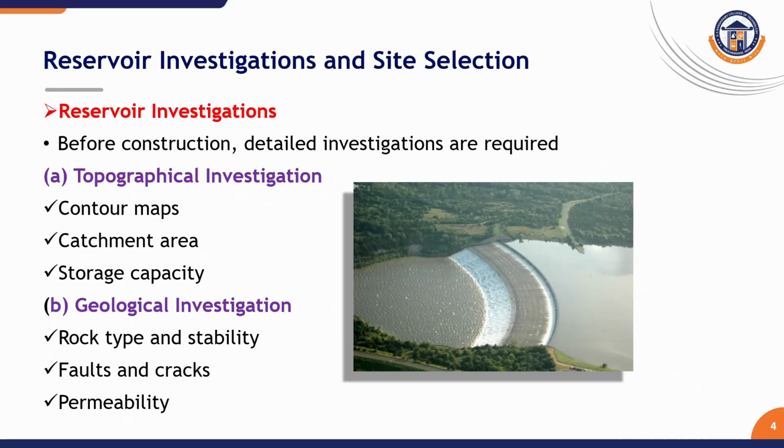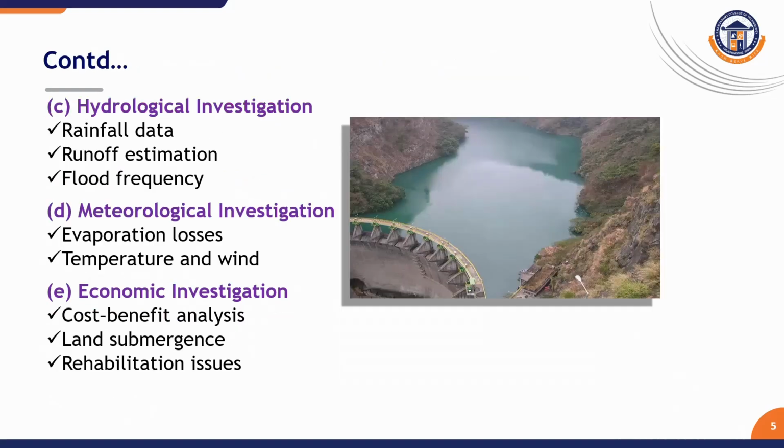Before constructing a reservoir, a detailed investigation is required. Topographical investigation includes contour maps, catchment area, and storage capacity. Geological investigation studies rock type, stability, faults, cracks, and permeability to ensure safety of the structure. Hydrological investigation involves rainfall data, runoff estimation, and flood frequency analysis.